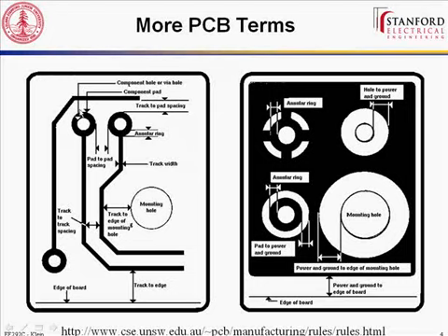And so when you come out to your top layer or your bottom layer, whichever side you're soldering on, there'll be an annular ring as well. And so your lead would be sticking through the hole, and you'd solder onto this ring just like you normally do. But it's electrically connected because the inside wall is plated in copper to this layer as well. You cannot put components inside layers.